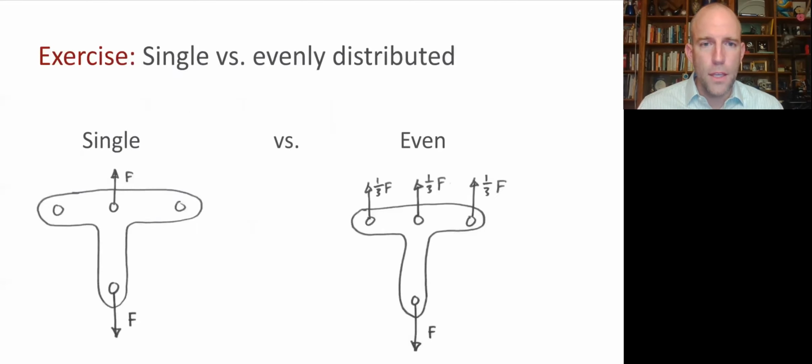simplifying assumption. So here are a couple of different assumed free body diagrams that simplify things in similar ways. So in the left-hand case, we say, all right, let's say there's no X force on those side holes, and what the heck, there's no Y force either. The whole thing is reacted out on that middle hole. And on the right-hand side, we say, well, we've got 3 holes and this one force down, so maybe 1/3 of the force is reacting out at each hole.